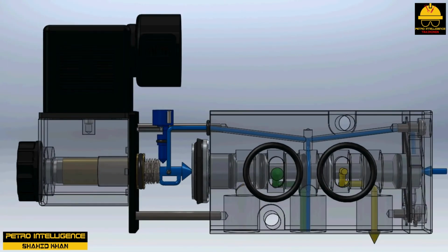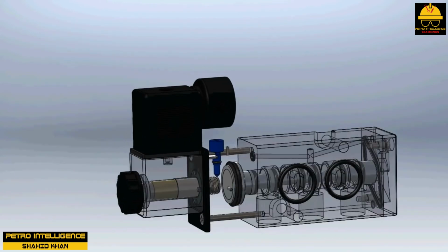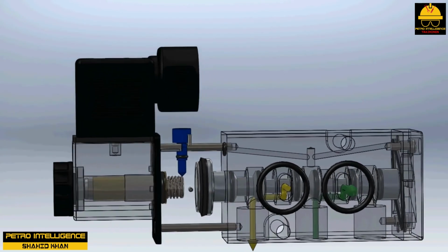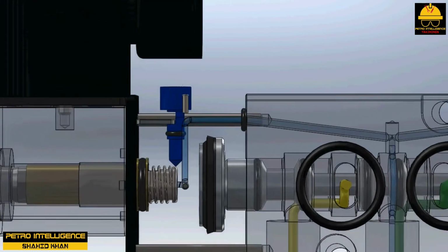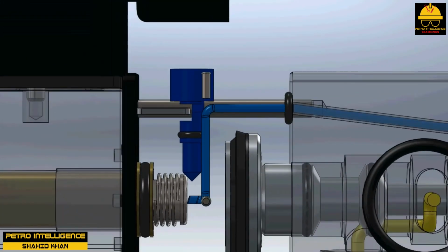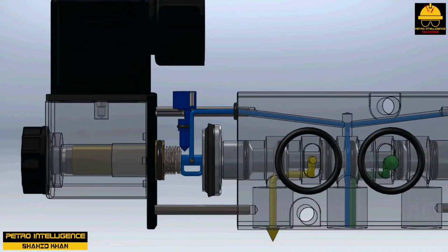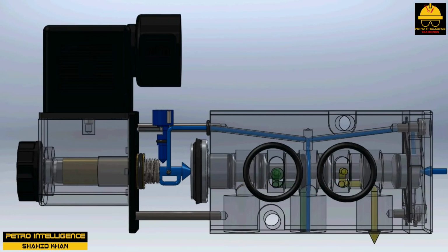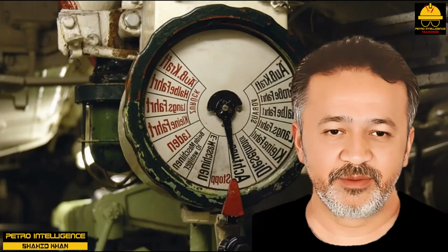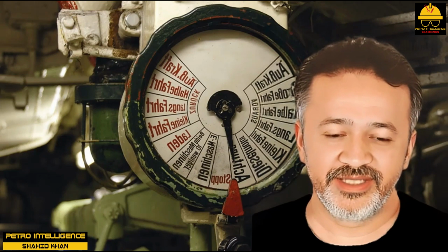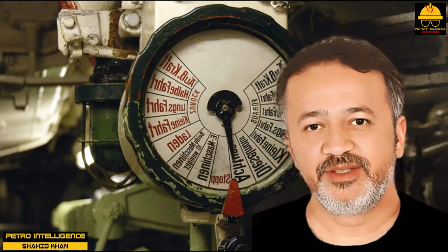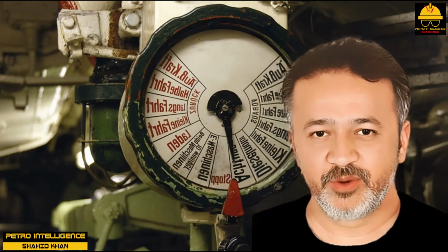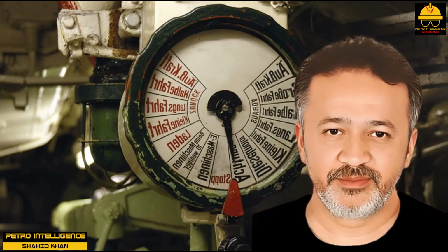A wire coil surrounds the upper spring and stem. When the wire coil is energized, a magnetic field is set up, causing the armature to lift and compressing the spring. The armature is held in place until the current stops. A motor-driven actuator is attached to the stem of a valve by a set of gears. Gear movement controls the position of the stem.